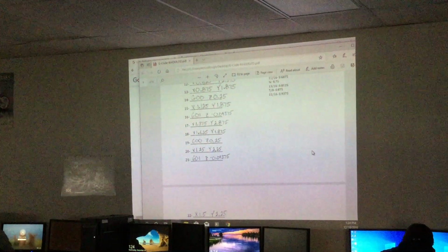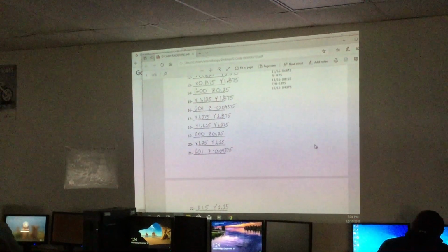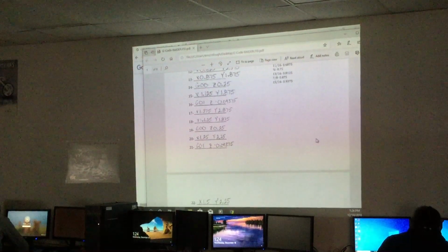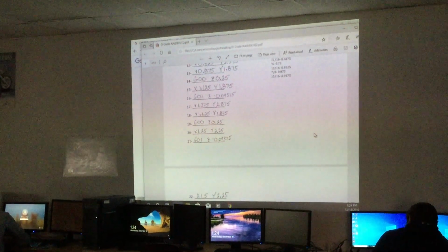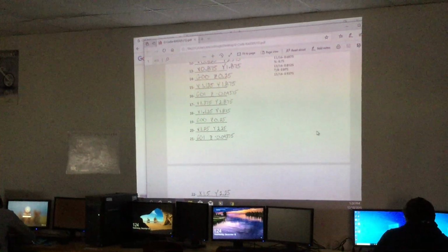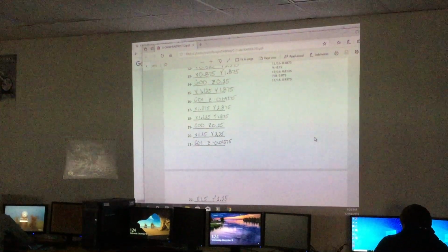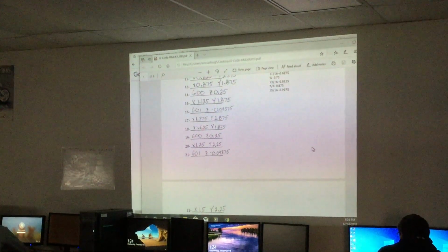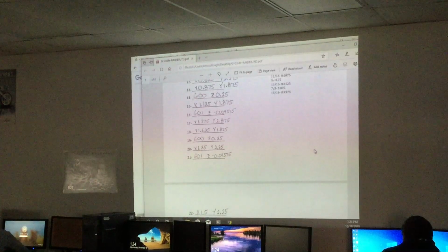Phasing, that's G01. Slow movement. So I went back to slow movement and told it to put the bit in that same depth again. And then 17, this is where I kind of think about my coordinates, because now I have to go up at an angle. So my X and my Y both change, right? And then the other side of the A, I just went right back down to that.